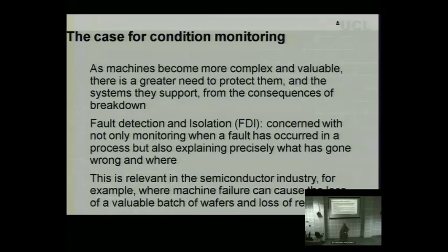For fault detection and isolation and monitoring, we're interested in change. That's what we're fundamentally interested in. So long as you've designed an observer with an A, B, C which nominally makes nu do nothing, or it can do 2 or 10 or whatever it is, but it does something fairly constant which relates to good performance, then the discriminator is really change in that estimate. So that's what failure detection and monitoring is all about.